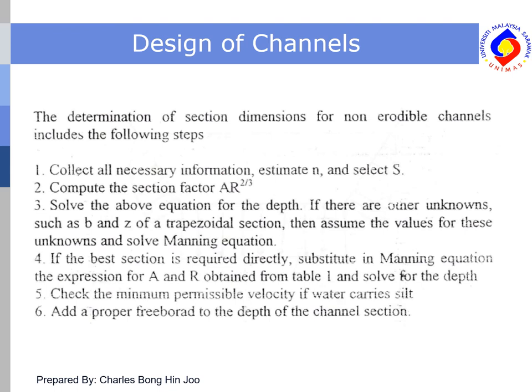Then we need to check whether the velocity meets the minimum permissible velocity requirement so that the water can carry the sediment or silt. And finally, add a proper freeboard to the depth of the channel section.